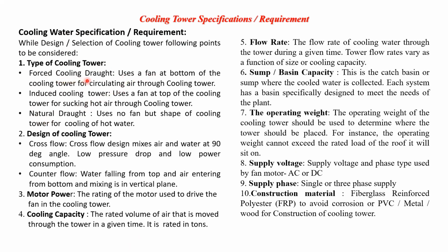So what is forced draft? It uses a fan at the bottom. Induced draft uses a fan at the top, and natural draft uses no fan. The basic principle is the same, only the position of the fan differs: at the bottom, forced draft; at the top, induced draft; no fan, natural draft cooling tower. How they work, we will see later on.